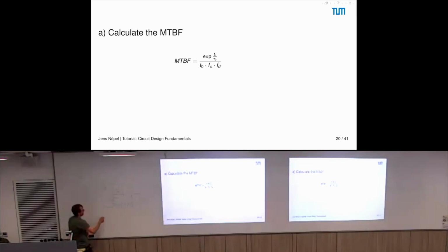If we now look at probabilities, then the probability that we fall inside this time window is just T0 over T_Fd, which is nothing less than T0 times Fd, all right? So this is the probability that such a metastability event can even happen.